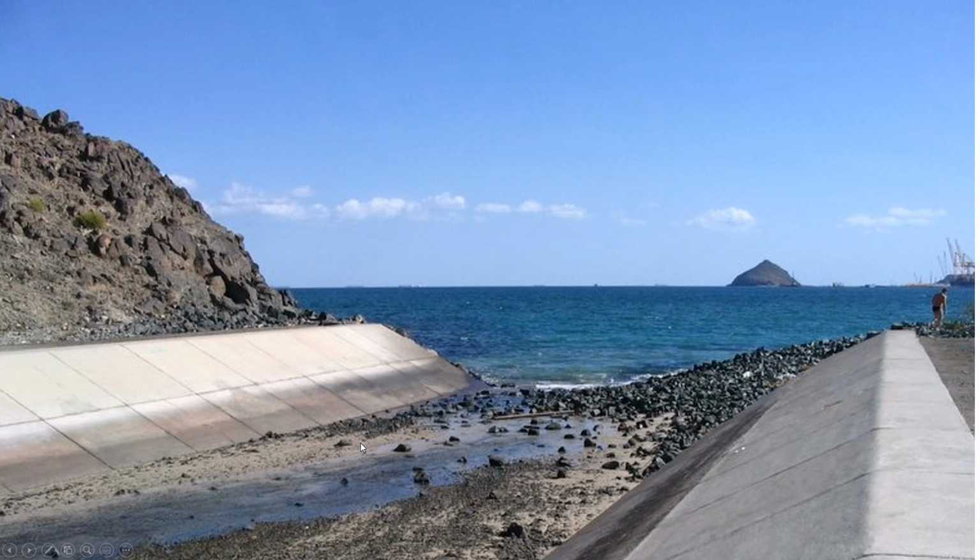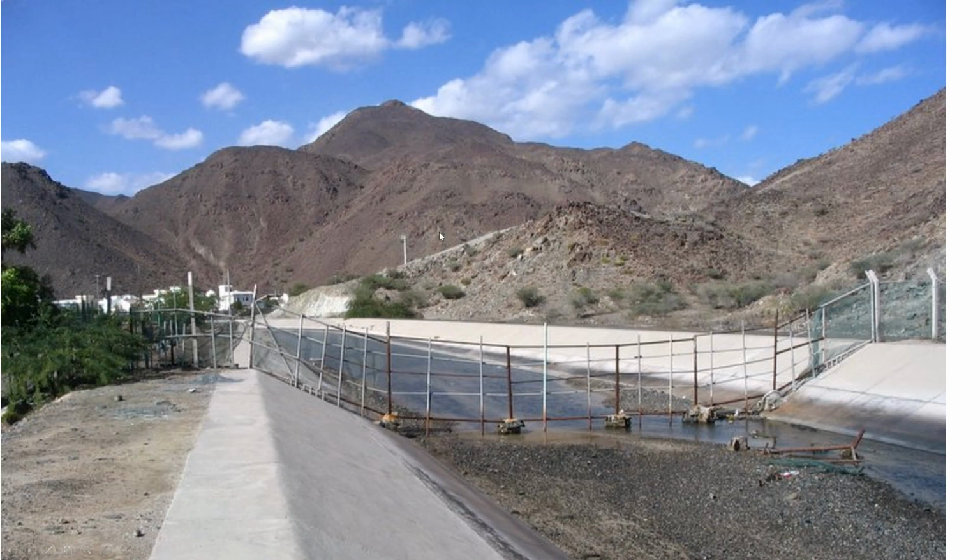So this is the part where the water just goes into the sea, and figuring out how wide to make that channel is a calculation that combines hydrology, which is studying the rainfall patterns and the earth characteristics, but then also the hydraulics. How much water can be conveyed in an open channel like this if you're making it smooth concrete, if you know the slope, what's the flow rate that can be carried by a channel.